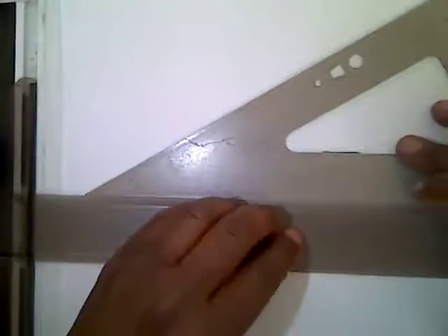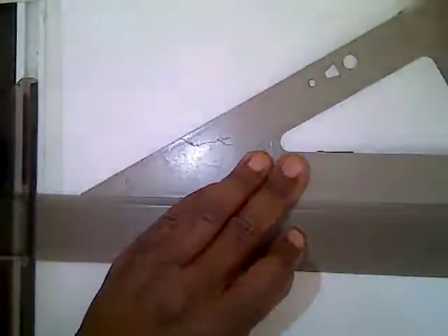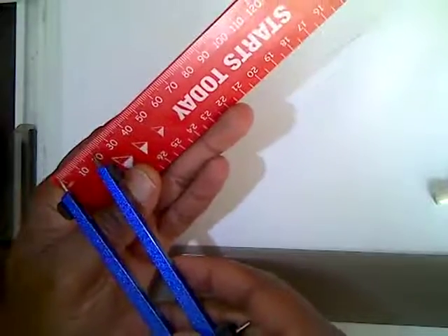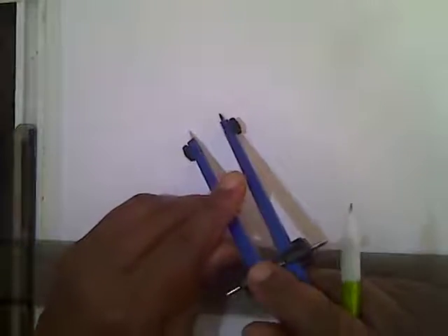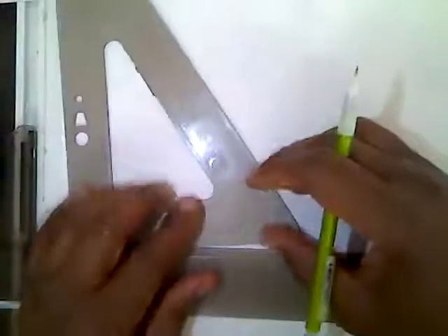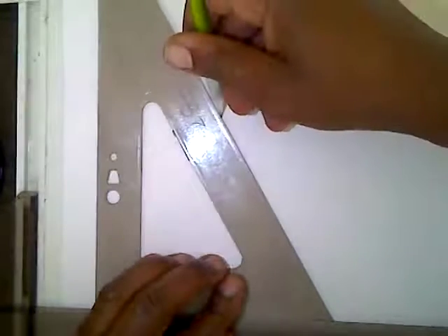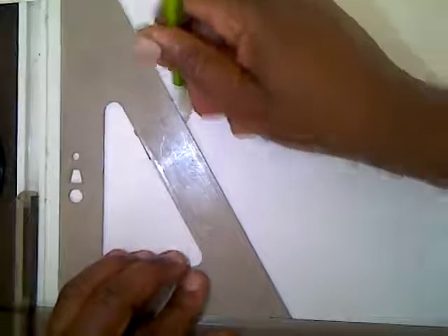Right, I will start with my auxiliary. I will draw it somewhere here. There are my faint lines, an angle of 30 degrees. I must measure 20. Each side is 20. Let's check. There is 20 for each side. Maybe I'd like to start here. That will be my 20. Drawing my 20. And then perpendicularly at 90 degrees, draw a line over there.